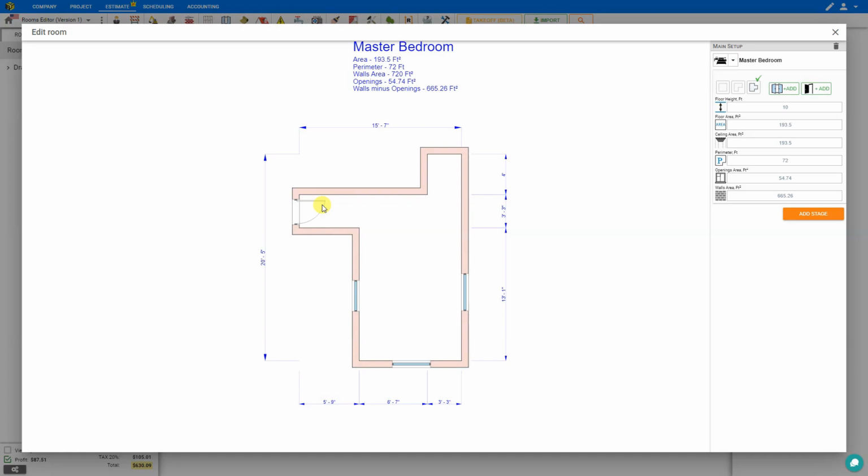So here we can select whether this is an inward or outward swinging door and whether it swings to the left or the right. So we'll make this an inward swinging door opening to the right, and we'll click to position that door. And now we can do the same thing again to position another door. If we want, we can put a door here by clicking on the wall, and then we have to set the position by clicking our mouse again. And we can place as many doors as we want as well.